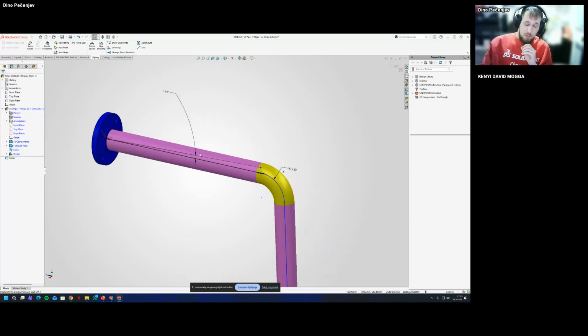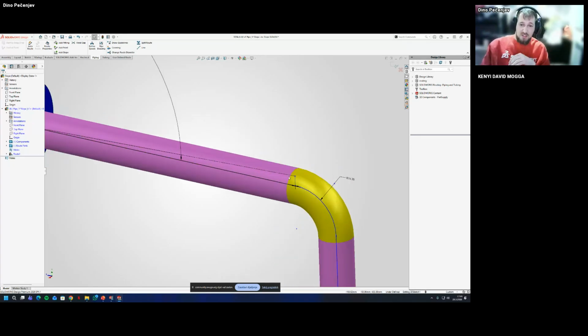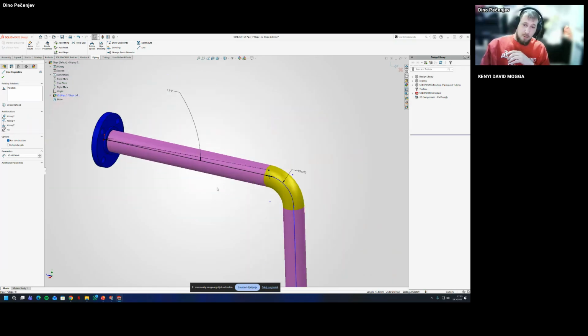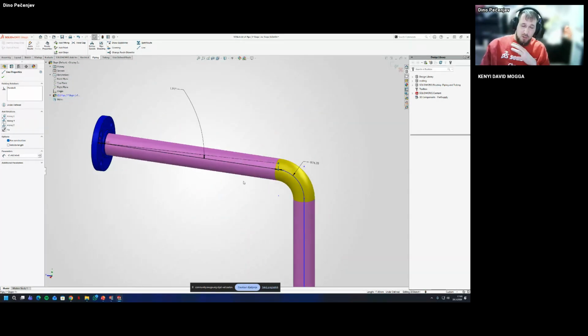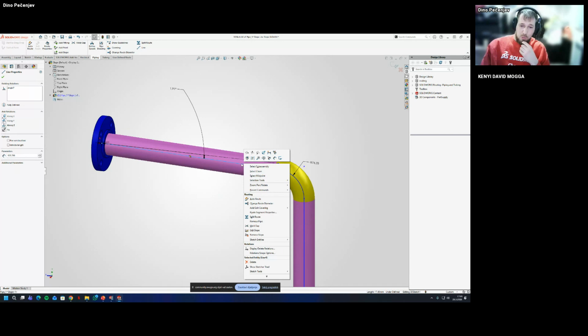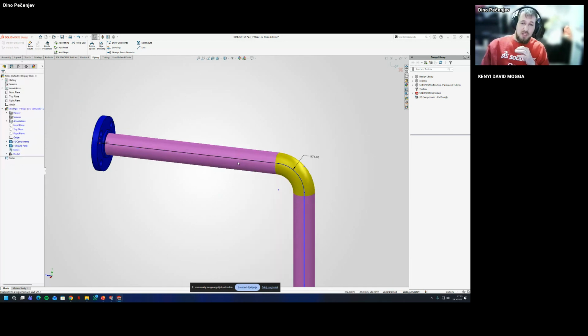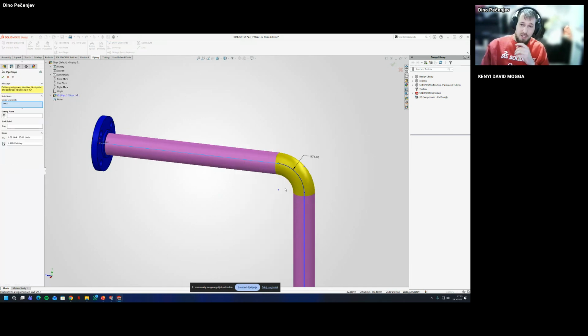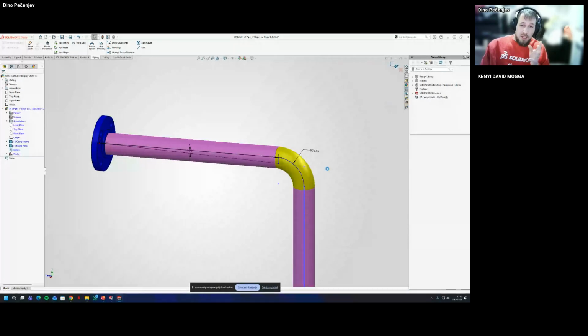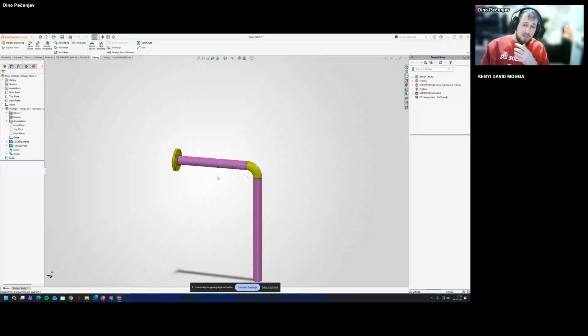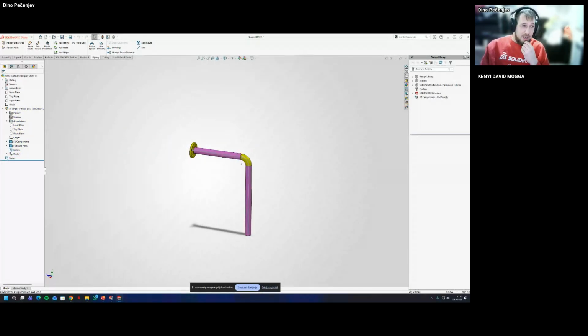For removing the slope, since the slope creates two center lines to actually create the slope, we're just going to right click and remove slope. It's a lot easier that way. So if we're adding the slope, it's the same thing again. So I'm just going to add it. And the slope is done under the angle I actually required.